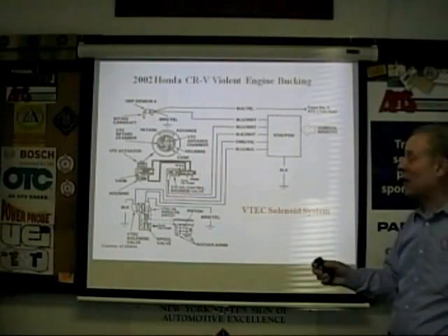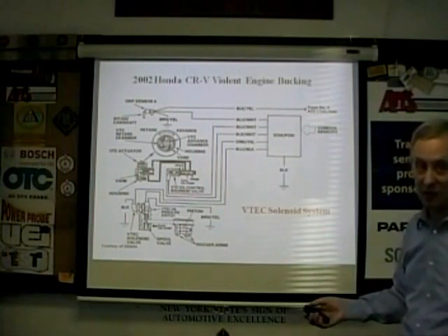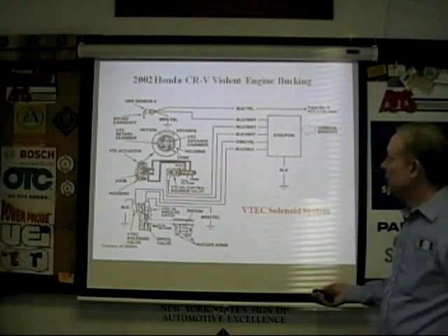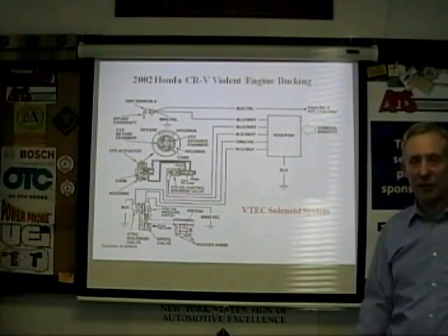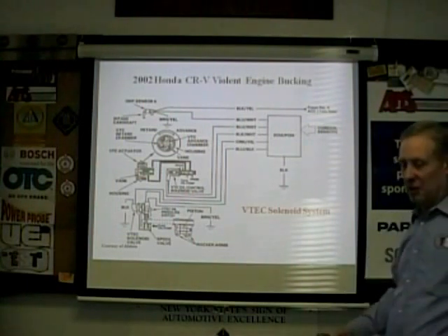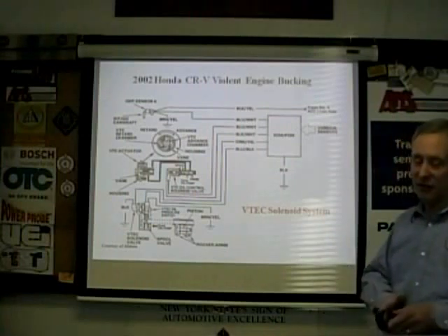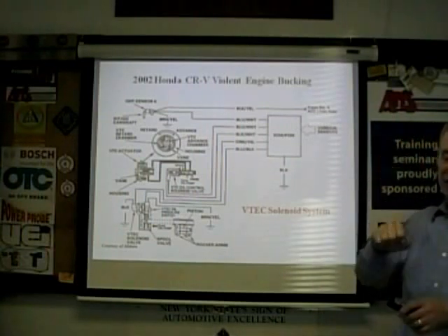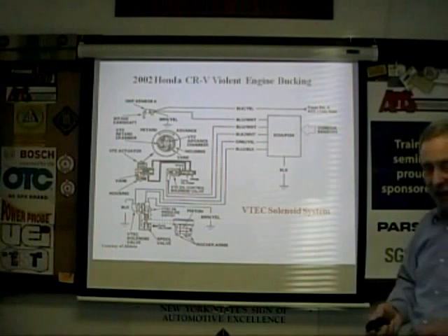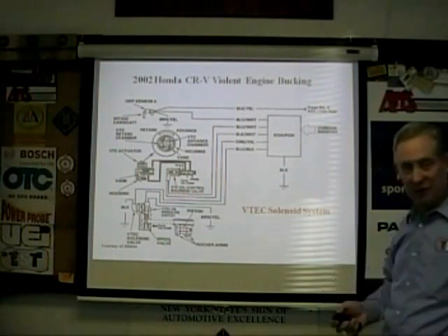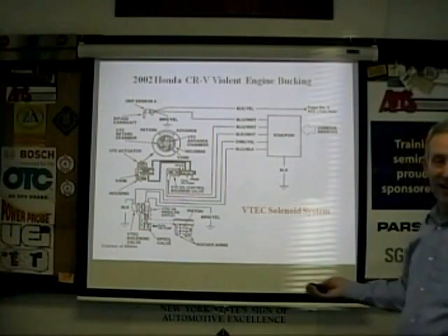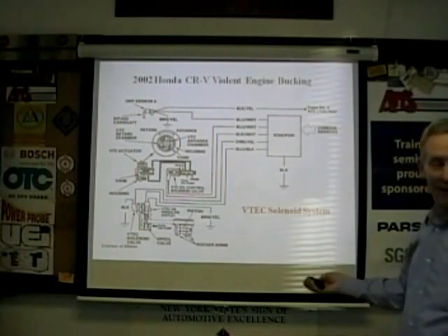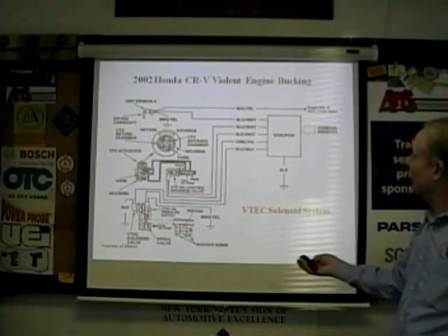It's different from Volkswagen, but very similar to what a lot of the Europeans are doing. They're using some type of arrangement, usually helical gears, to change cam timing. VW does it a little differently. They stretch the chain, they move the chain between the two cams. Kind of a weird thing. And fun to work on.